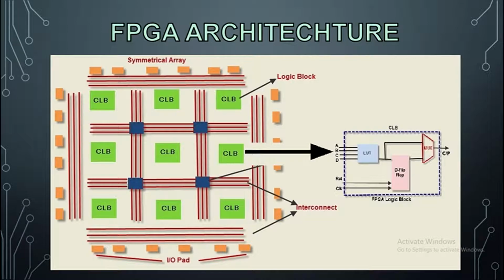So this combination of inputs, also called addresses, is stored in the SRAM-based configuration memory. This helps us change only the combination of inputs in the SRAM to implement any logic gate or Boolean equation. In this way, the LUT is a very important block of a CLB. So in this way, FPGAs are denser and faster than a CPLD.